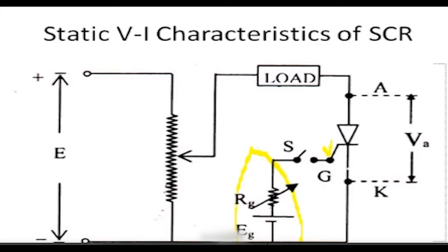Similarly, in the case of this SCR also, even though J2 is blocking the current, it is still a semiconductor switch, not a mechanical switch. The regions are not isolated. The regions are separated by junctions. If the regions were isolated, current would be zero. But these regions are not isolated. They are separated, just like our Telangana and Andhra. They are separated, not isolated. There is a difference.